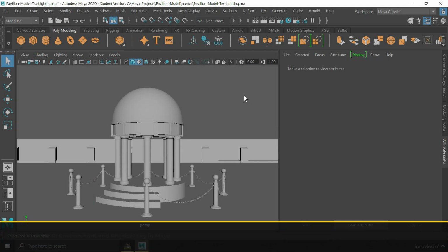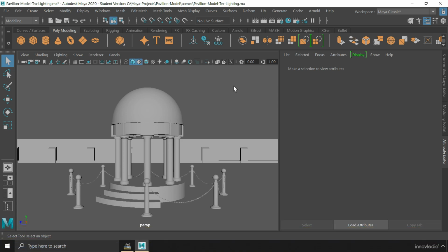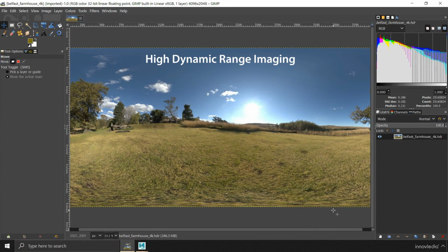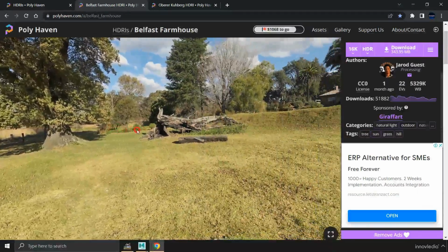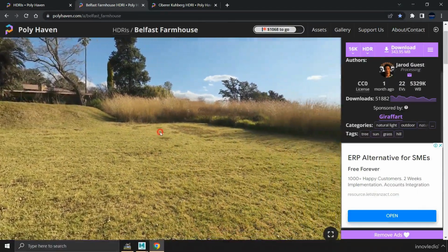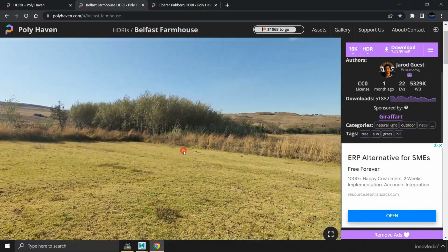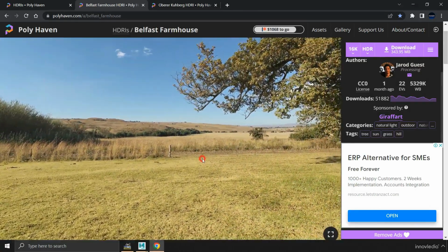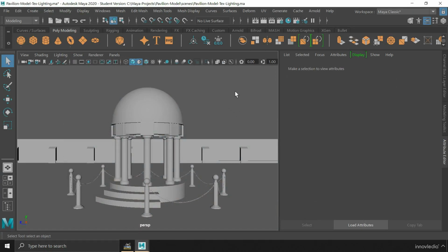Hello and welcome back. In this video, I'm going to show you how to do image-based lighting using an HDRI and use the physical sky system in Maya. The full form of HDRI is High Dynamic Range Imaging. An HDR image is a 360-degree image or photograph of a place with a lot of color information that is wrapped on a sphere in a 3D space to simulate a real-life lighting condition. You will understand it once I demonstrate its use inside of Maya.